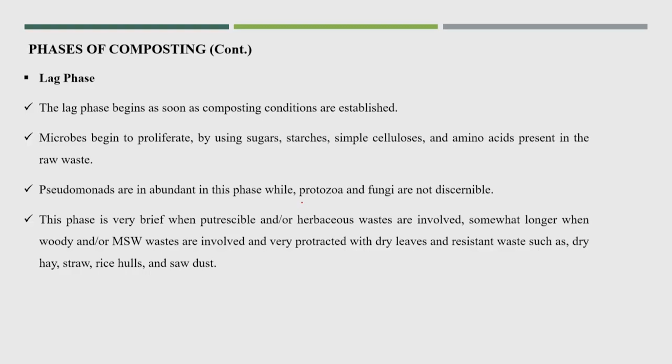This phase is very brief when putrescible and other kinds of waste are involved, otherwise it is somewhat longer when woody or MSW waste is involved. Woody means there is more hemicellulose and lignin, so that phase could be longer. Dry leaves also contain a large percentage of lignin.